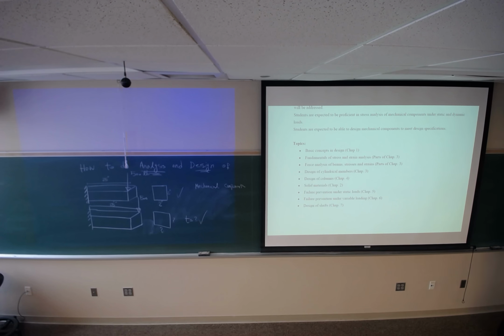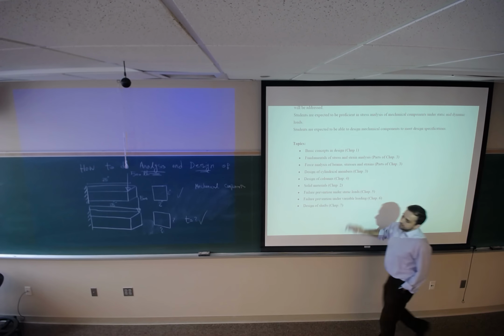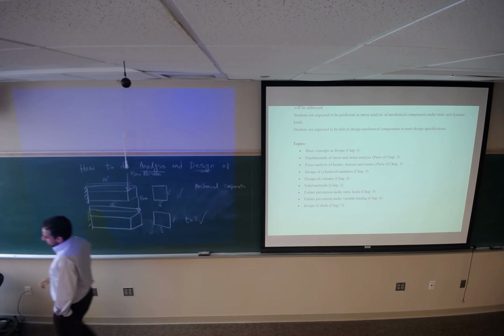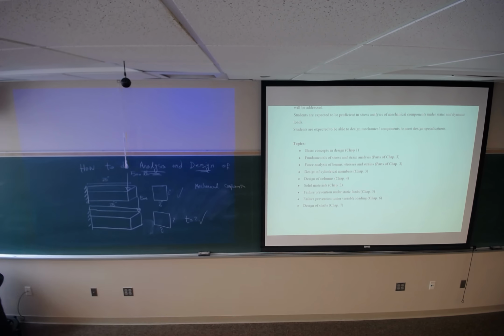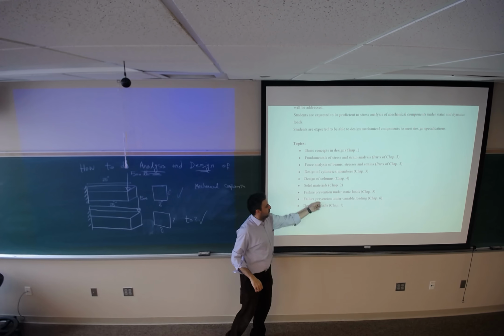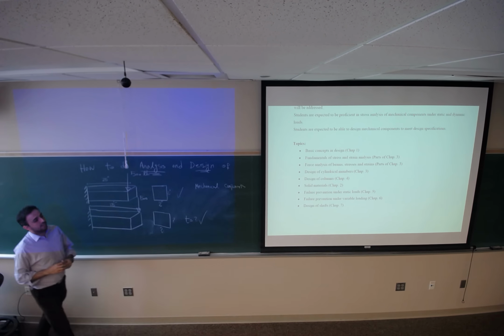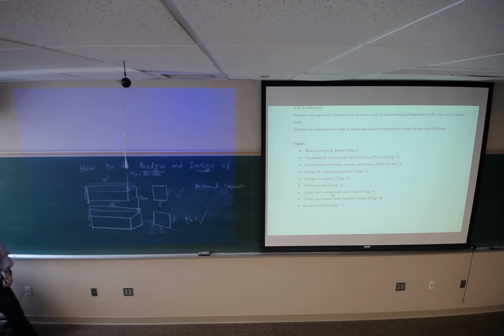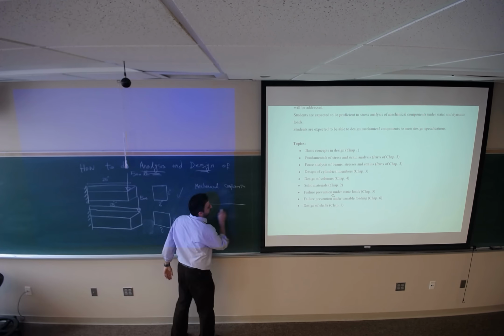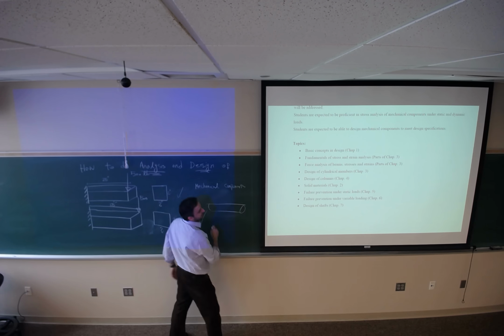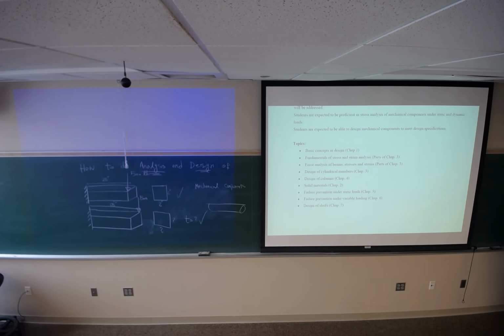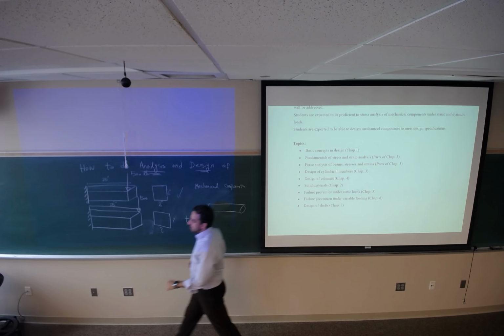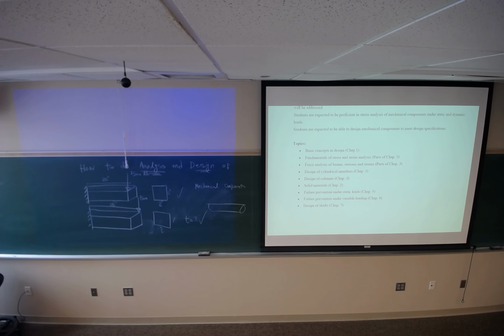If this 500 pounds is changing, suppose it's varying between 0 and 500 pounds, then we are going to have another problem here, which we call fatigue analysis. We go through that concept, which is new for you. And then after we cover the fatigue, we can talk about the shaft, because shafts are components under variable loading. The loads on the shafts are changing, so we need to cover the fatigue before we go to the shaft analysis.